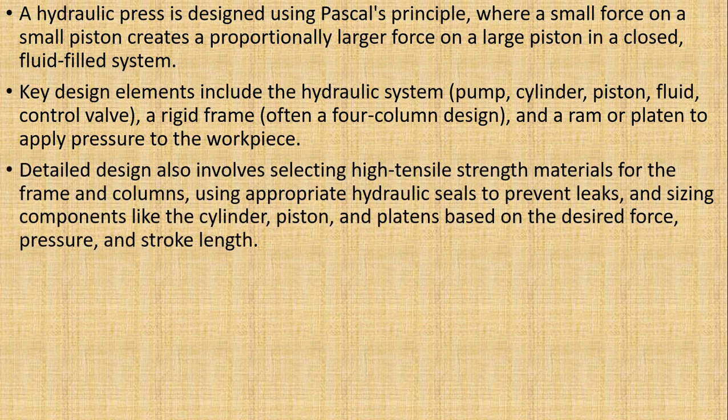Detailed design also involves selecting high tensile strength material for the ram and column, using appropriate hydraulic seals to prevent leaks, and sizing components like the cylinder, piston and platens based on the desired force, pressure and stroke length.